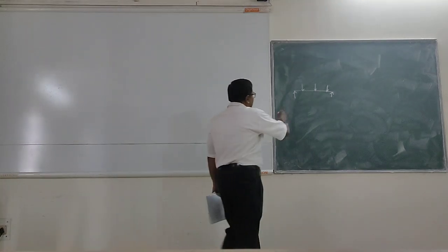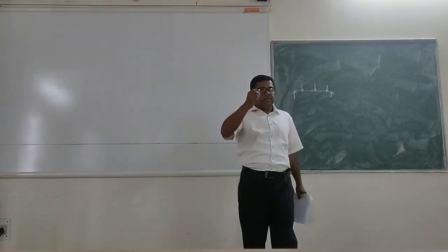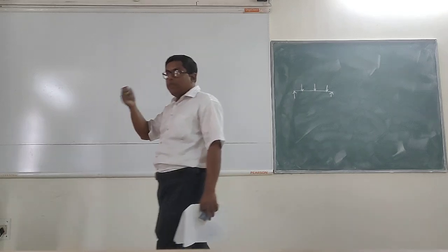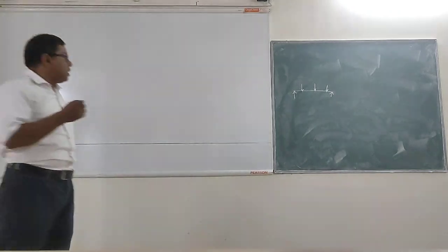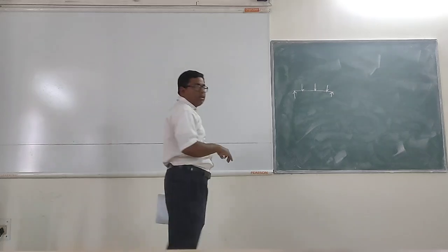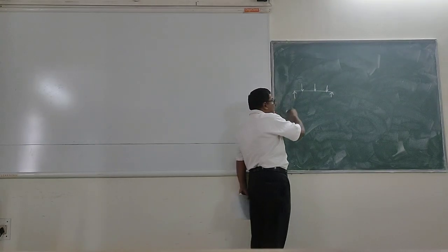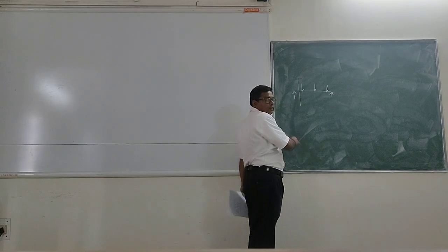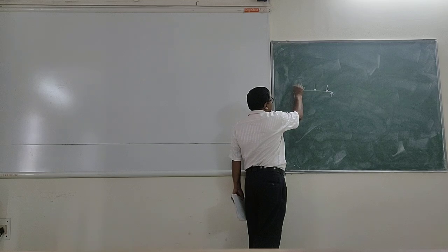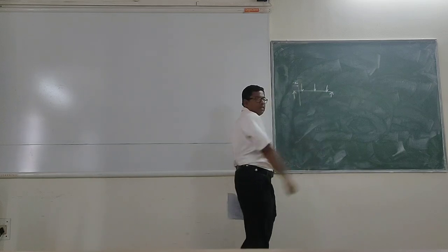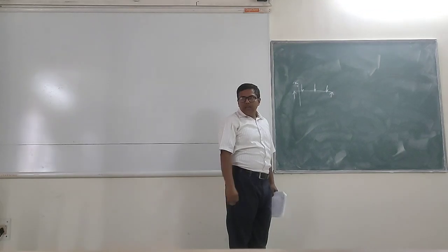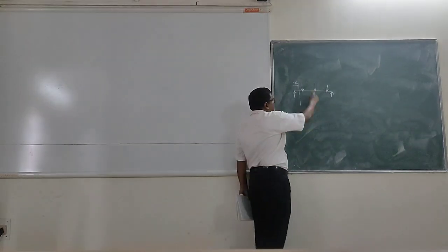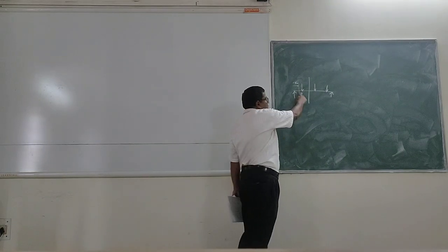So you see, for the problem of solving it using direct application of the double integration method, how many sections do you need to take? I have 3 loads. So one section will be here. If I start varying x from this direction, I will have to take one section over here. Next, I will have to take another section over here because the load is changing.